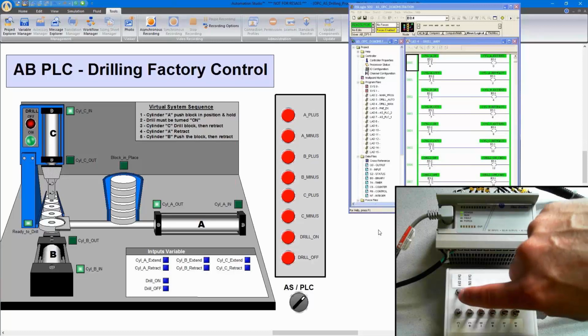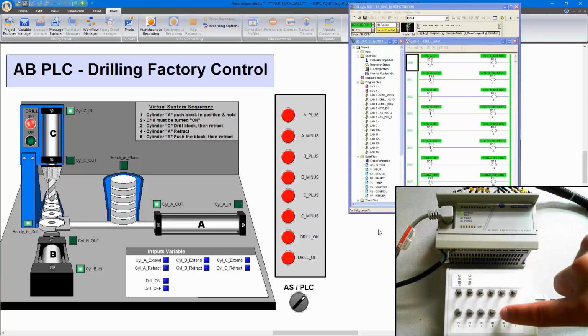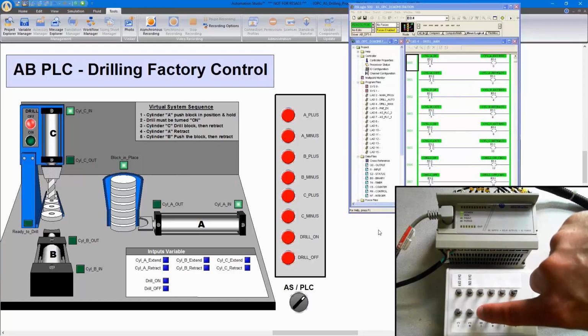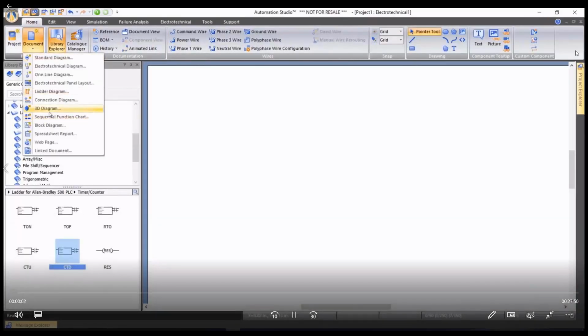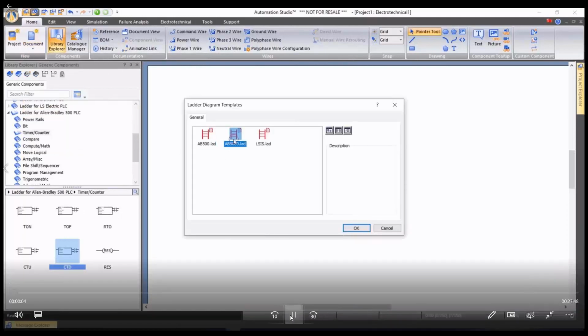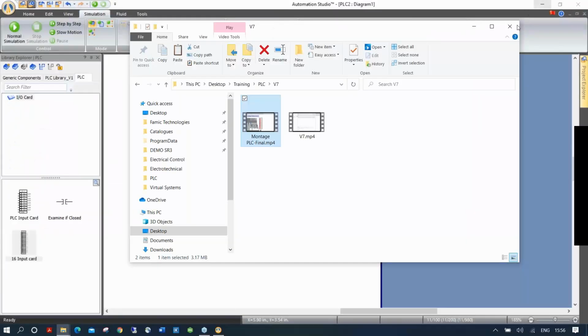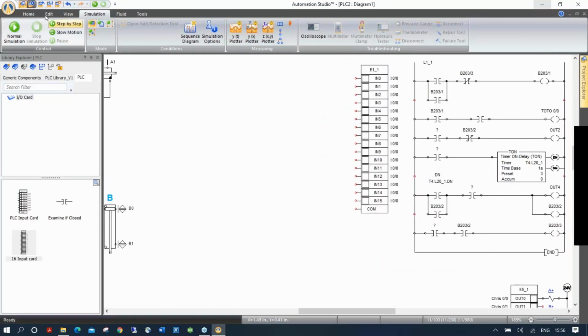Okay, we often use Kepware here as an OPC server. It's a free server that supports many brands of PLC, and it runs for 2 hours, and then you can just stop it and restart it and do it again, okay? But you can actually communicate. So any tool that has an OPC server, you may use. Arduino units, some of them have an OPC server in them, okay? So this is something I wanted to share with you about what could be done with the OPC connectivity and the PLC. So this is pretty much what I wanted to show you.